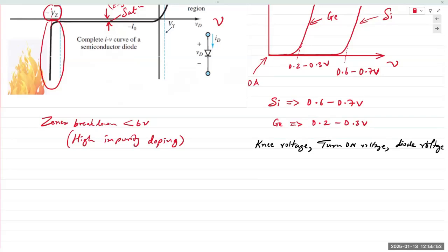And then another process takes place that is known as impact ionization. These charge carriers acquire enough energy that they are now moving around at random inside the material. When they move, they collide with other atoms and displace more charge carriers. Let's say one collides with an atom, breaks 2 more and creates 2 more charge carriers.